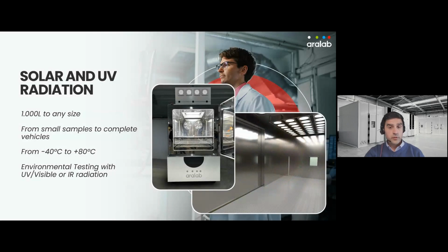Solar, UV, and radiation. I was mentioning, what happens if you put your cell phone on the dashboard of your car and you go to the beach and you forget about it, and what happens when you come back. That is also tested, usually in this type of chamber. It must be noted that the chamber still has full operating capability, but usually when the light is exposed, that capability is decreased. So usually it's operated from -40 to plus 80 degrees Celsius. And then the light itself can be UV, visible, infrared, or a combination of all these. They can be adjusted.